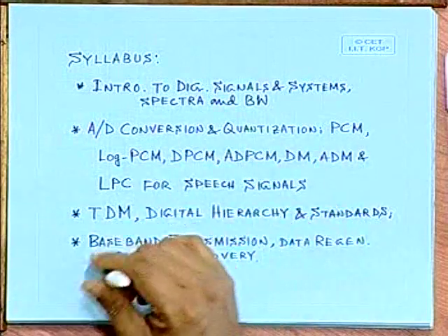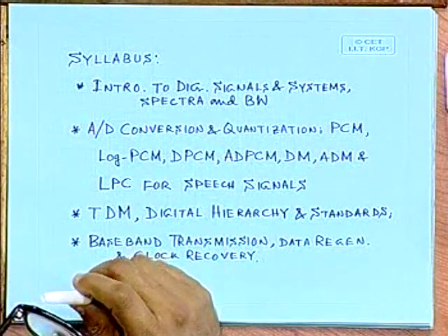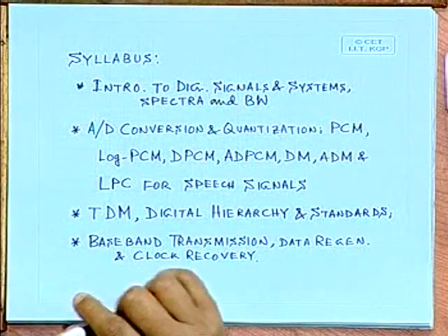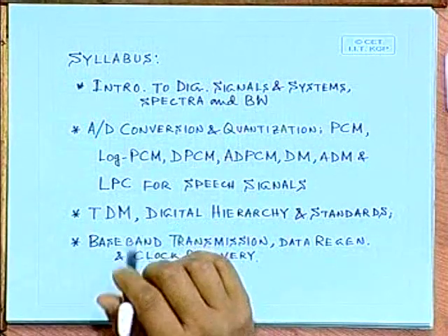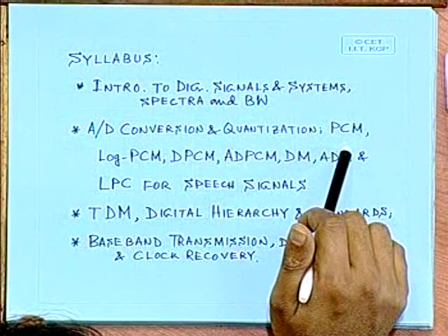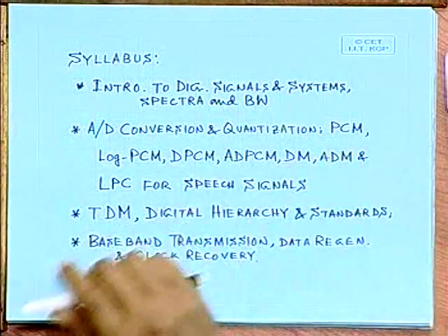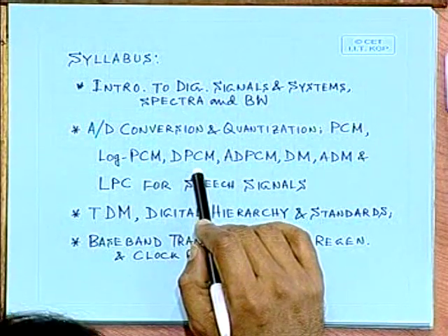Another very interesting variant of pulse code modulation is known as differential pulse code modulation, or DPCM. We will see that the purpose of differential pulse code modulation is to reduce the average number of bits that otherwise would have to be transmitted following a more classical PCM technique. Transmission of a digital signal through a wireless medium needs some transmission bandwidth, and if the average bit rate of transmission is higher, we need higher bandwidth, while every other feature of the system remains constant. So it makes sense that we try to reduce the bit rate of the signal which has been digitized. DPCM is one elegant way of serving that purpose.